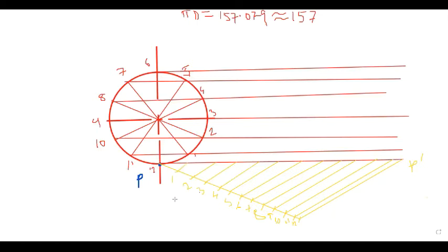Clear? Here, if you use the compass, you see this gap all remains the same. Okay. Here it is not drawn according to the dimensions, so the gap will not be uniform. So basically the method will be, first you draw any line less than 90 degrees and divide it anywhere into the required 12 equal parts. By taking any measurement by compass, divide this line into 12 equal parts, and join last point to last point. Okay, then draw the parallel line at each point, 11, 10, 9, and up to 1, and here you give the names.